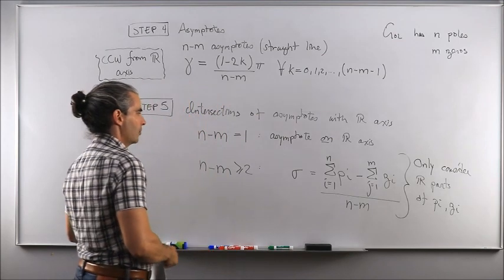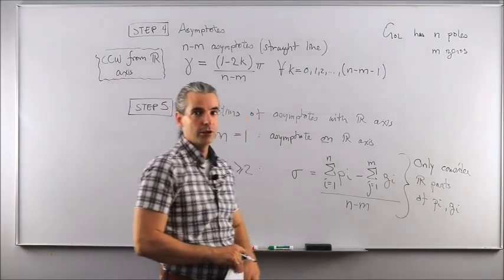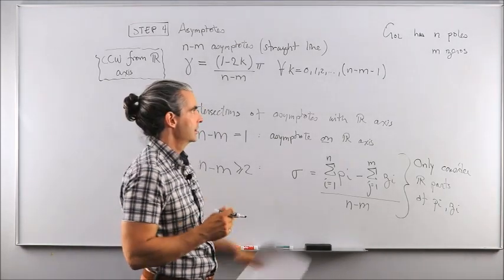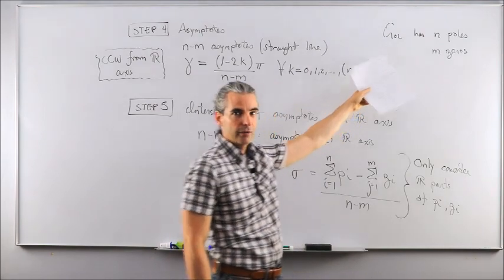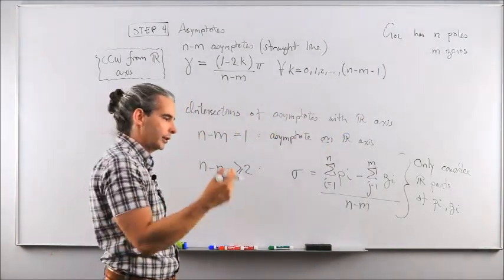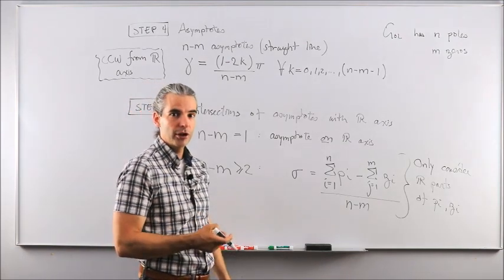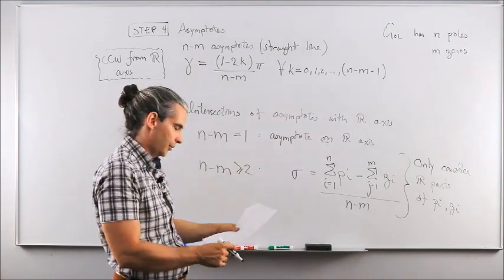Poles and zeros of what? Of the open loop transfer function. So unless otherwise noted, everything is done from the open loop transfer function's perspective. There's only one step in the entire procedure for which you'll need to calculate the closed loop transfer function and use it. But otherwise, everything is done with the open loop transfer function.